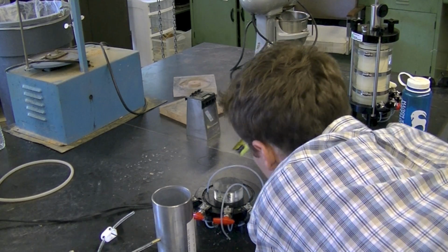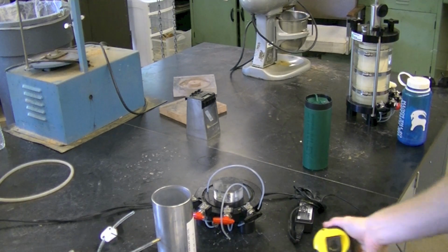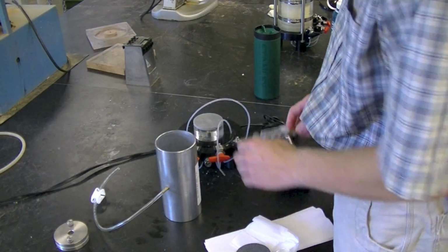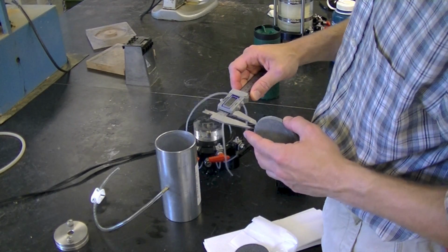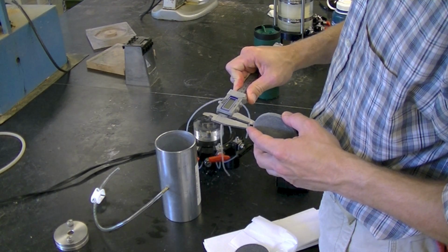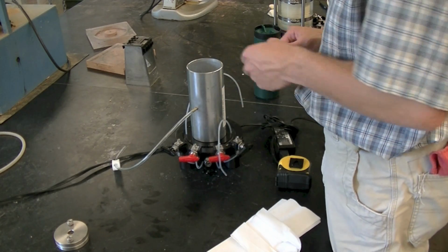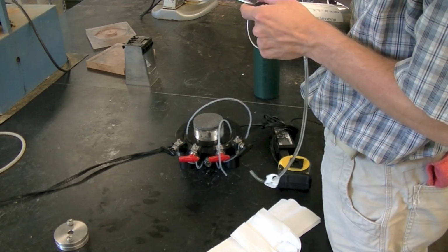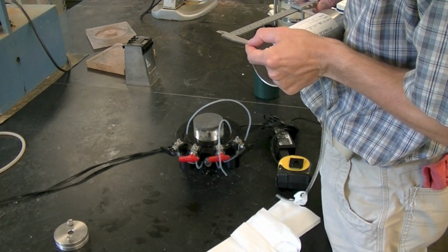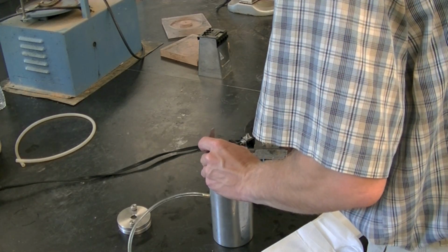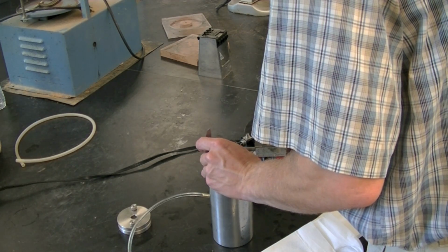Measure the distance from the base of the pedestal to the top of the bottom platen. A porous stone will sit on top of the bottom platen, so measure the thickness of the porous stone. The triaxial mold will slide down to the base as such. Now average a series of length measurements of the mold. Also average a series of diameter measurements for the mold.